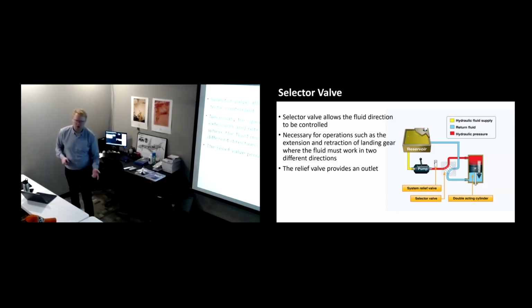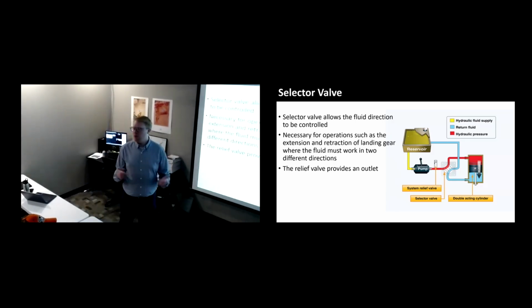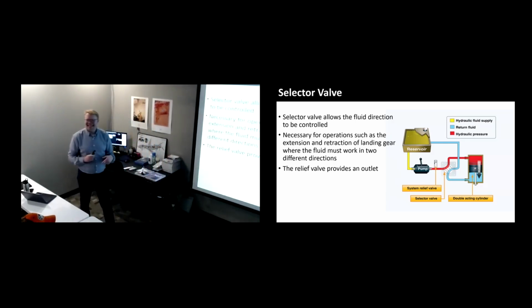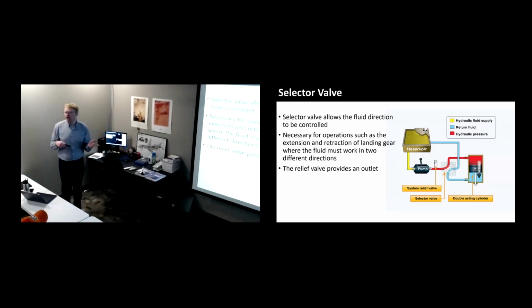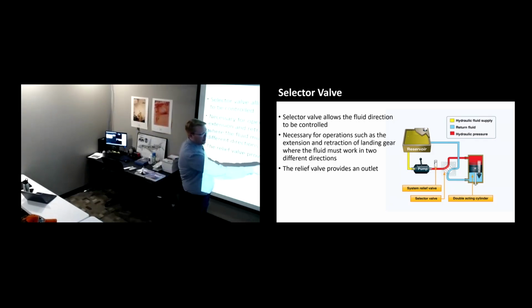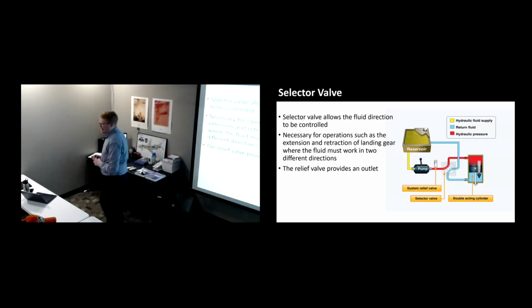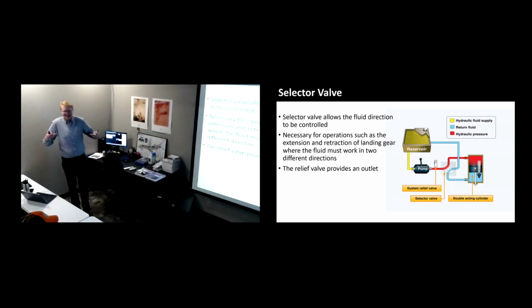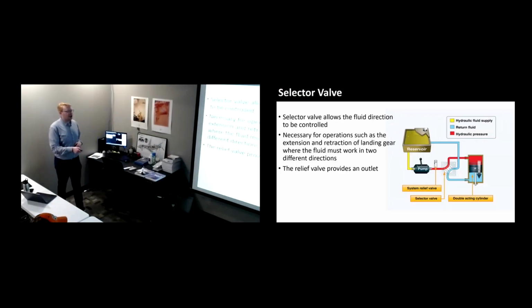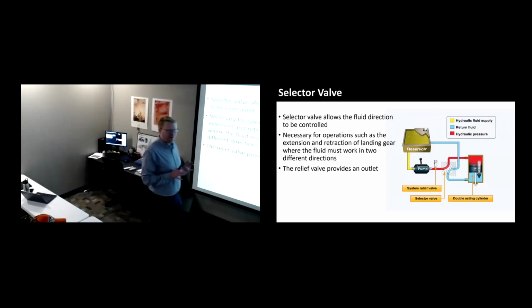What I mean by that is an ability here to move from one direction to the other. Sometimes you have a single pump that goes in a certain direction. Some will have a reversible pump that moves things in both directions. That's not brakes. Brakes go in and then release. A landing gear for extension and retraction is usually one of those reversible pumps. What I mean by that is a brake will just put fluid on one side and then allow it to release. Whereas a reversible pump will force fluid onto one side, release, and then force fluid onto another side and release. This is what a landing gear in a Piper Arrow has. There's a retraction side and an extension side that allow the wheels to come up and down. So pumps can change. A relief valve is usually installed here. Those are for pressure. Remember, all this fluid is under pressure.